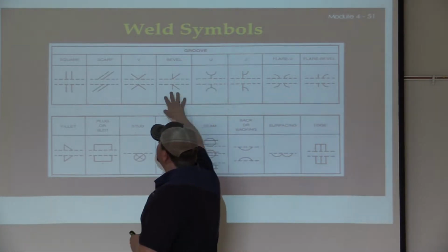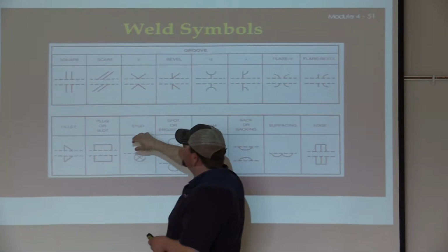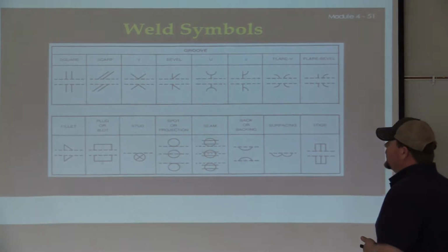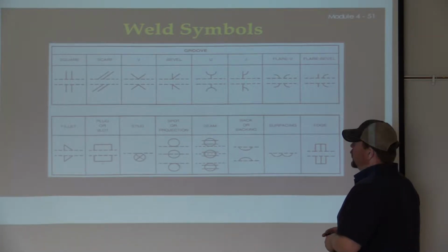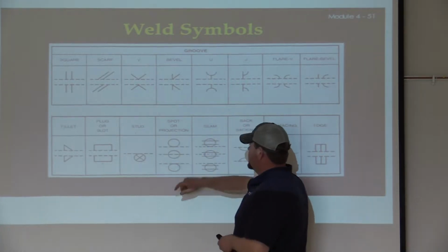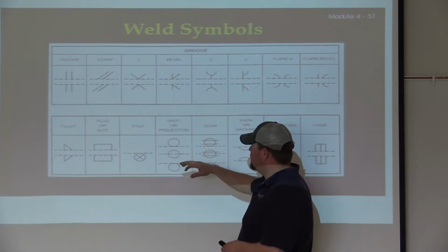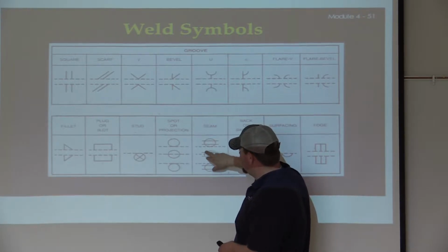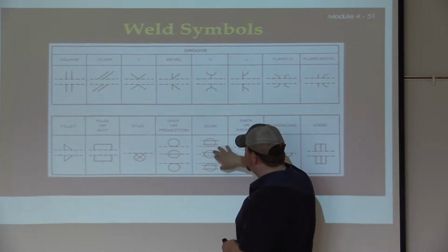And then we actually get into, this is our prep, what type of joint it is, right? We just talked about these, but then what type of weld are we going to use to fill up that joint prep? Okay? So these ones here can be confusing between seam, spot, or projection. Again, I don't know that I've ever seen a projection weld. I do see seam, and the way I think about it is think of those railroad tracks, and I talked about the rollers going down. That's how they track those on the seam welds.